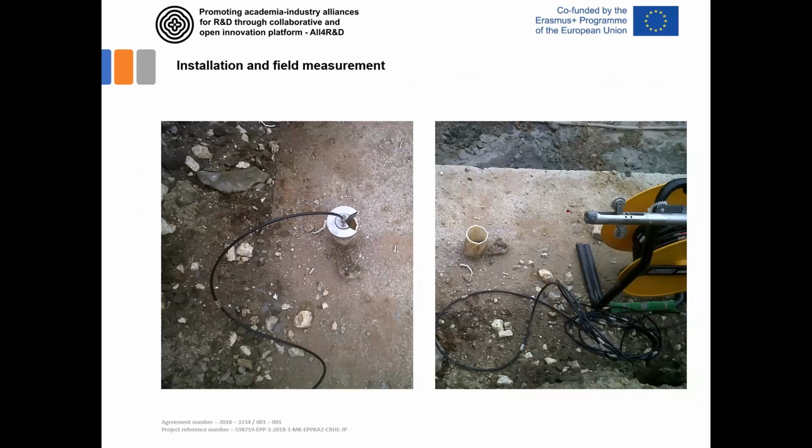Inclinometers are not always installed in soil or rock. Sometimes they can be installed in a structure. How do we do that? Well, it can be installed, for example, in piles. When you drill a pile, after that we install the reinforcement cage in this borehole. The reinforcement cage consists of main longitudinal reinforcement and stirrup reinforcement, spiral stirrups.